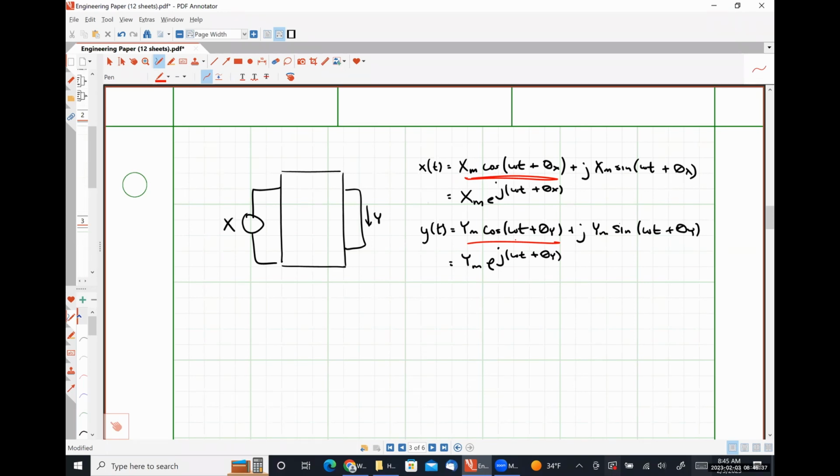So effectively, we can analyze a circuit using a complex number and then only take the real part at the output, and that will be the exact answer we're looking for, which is exactly what we noticed when we saw that our magnitudes were the same and our phase angles were the same when I had you guys plug it into your calculator using complex numbers. Okay. So using complex numbers makes it easier.